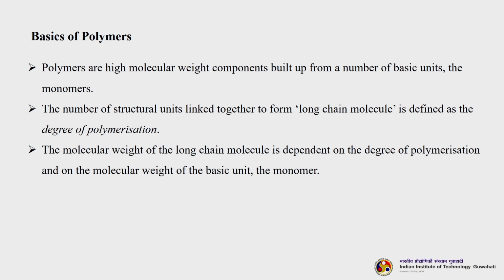So, let us discuss some of the basics of the polymers. Polymers are high molecular weight components built up from a number of basic units, the monomers. The number of structural units linked together to form a long chain molecule is defined as the degree of polymerization. The molecular weight of the long chain molecule is dependent on the degree of polymerization and on the molecular weight of the basic unit, that is the monomer.